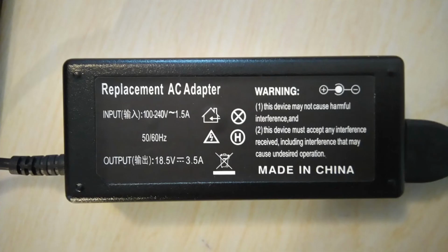Behind this charger, I can see input and output. The input is saying 100 to 240 volts. And guess what? I can see something like this, which is what? AC. So this charger can receive from 100 to 240 volts. That means it can work in any country. There are some countries that only use 110 to 120. Other countries also use 220 to 240. In our country, we use 220 to what? 240. So I can see 100 to 240.